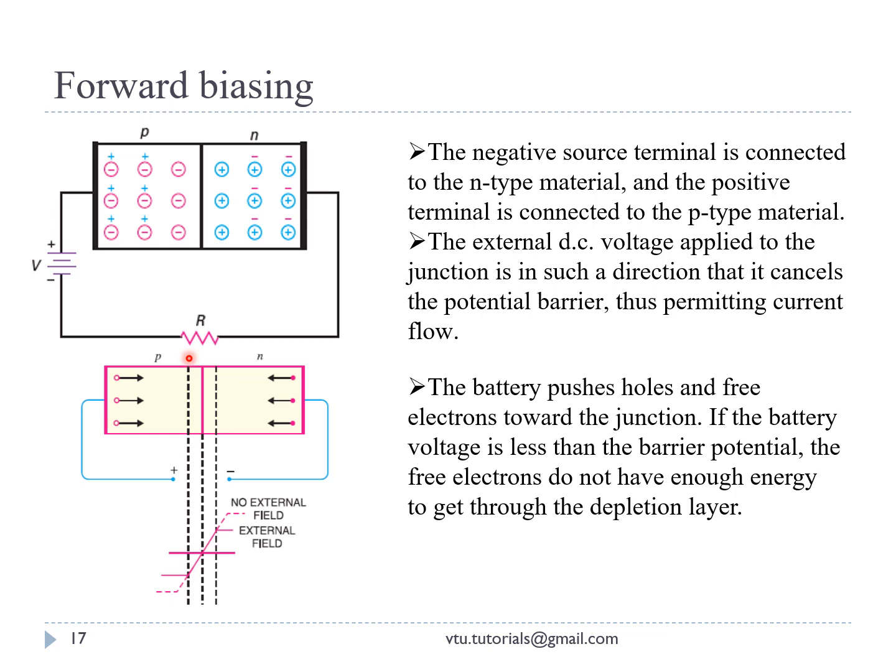So these free electrons continuously enter the right end of the diode, and holes are continuously moving towards the N type. This continuous movement of the free charge carriers will result in the current flow. As the potential barrier is very small, there will be a small forward current.